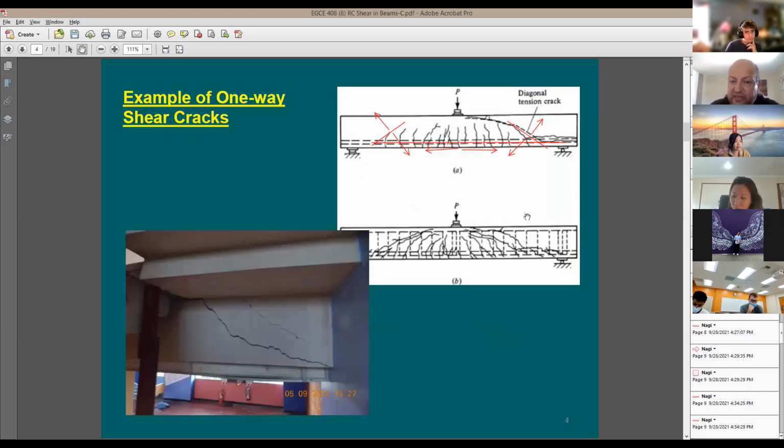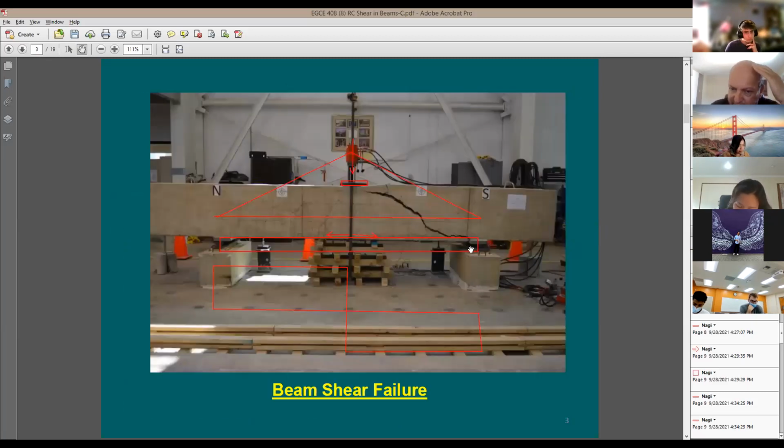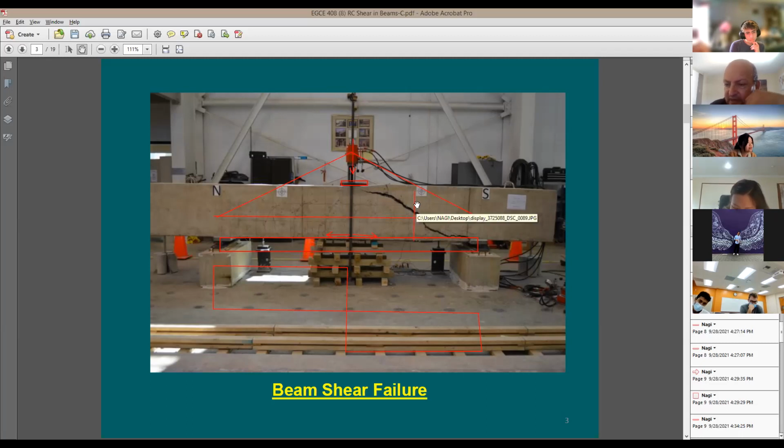You remember the length of this crack is how big? This looks to me maybe like 2 feet, maybe 18 inches at least. Look at this distance here. I'm going to put only one tie here. Does it make sense to you? Would one tie do anything? You can see no. I need more than one tie to be able to gain good strength. So the spacing needs to be in there.